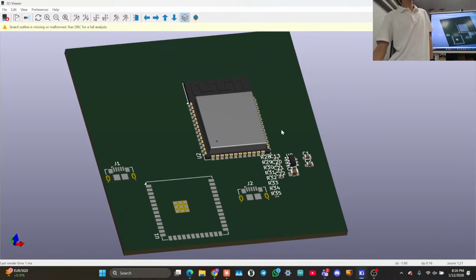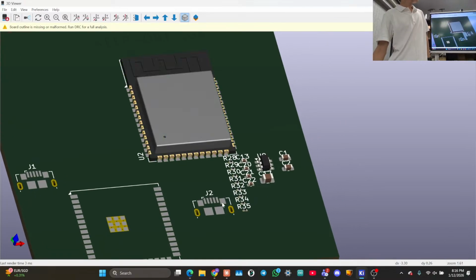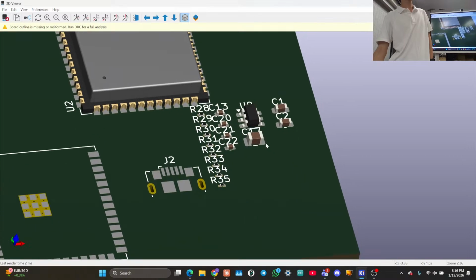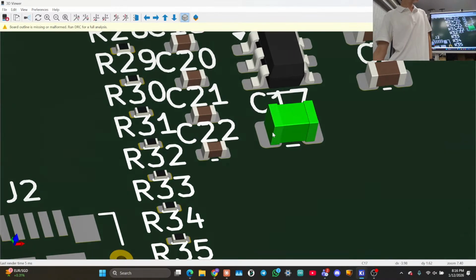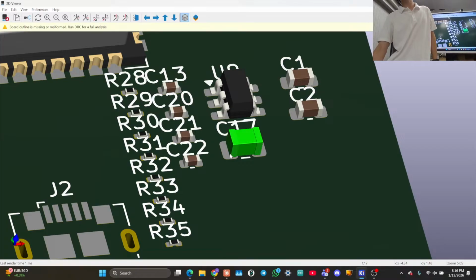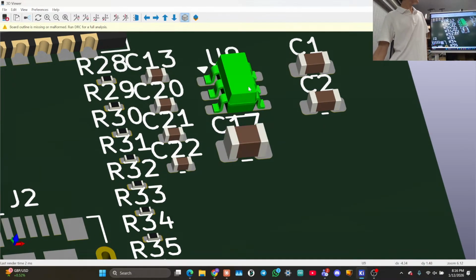You might not be able to do this because I set up all the 3D models already. But I'm just showing you how it will look when all the components are placed. Here's my SMD capacitor, and here's the pad it was mounted on. Then we solder it to the pad. So this is the importance of footprints. If your footprint is wrong, my chip does not actually have pads to solder onto, so how am I supposed to build the board? That's what the footprint is.